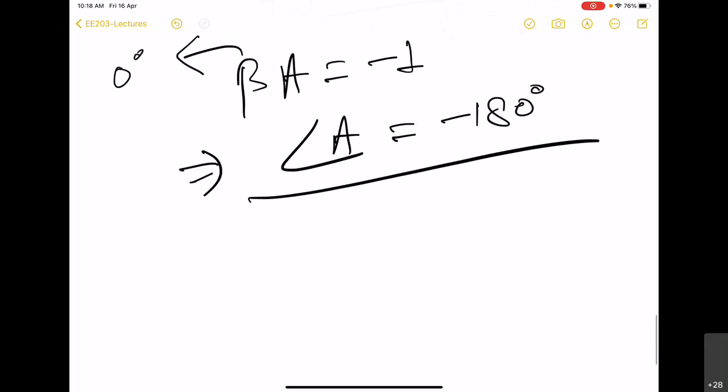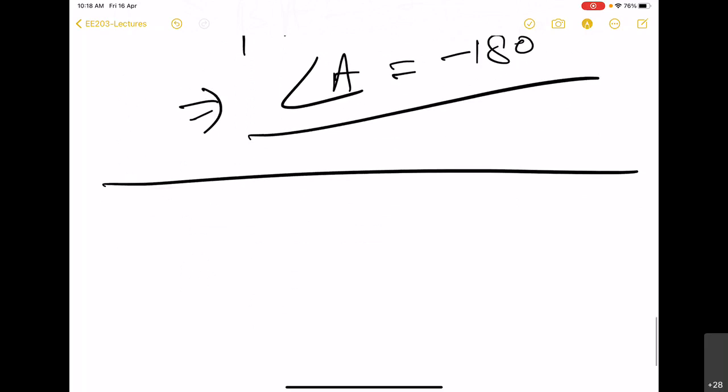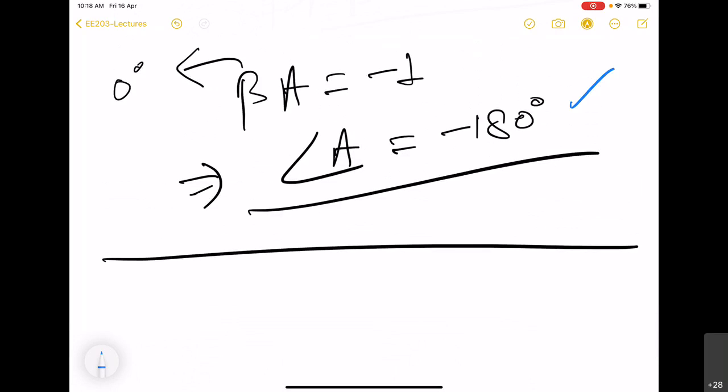So now we will be more specific, and we will take amplifiers of various order, first order, second order, third order, and put them into a negative feedback loop, and then try to see which of the amplifiers will satisfy this Barkhausen criteria, or alternatively which type of amplifier will give rise to phase of beta A equal to minus 180 degree, or the amplifier itself maybe.